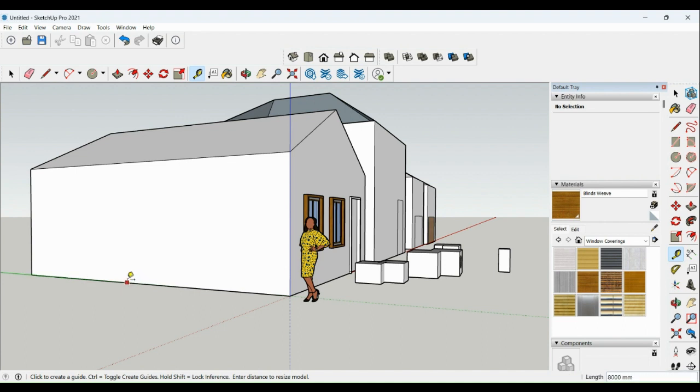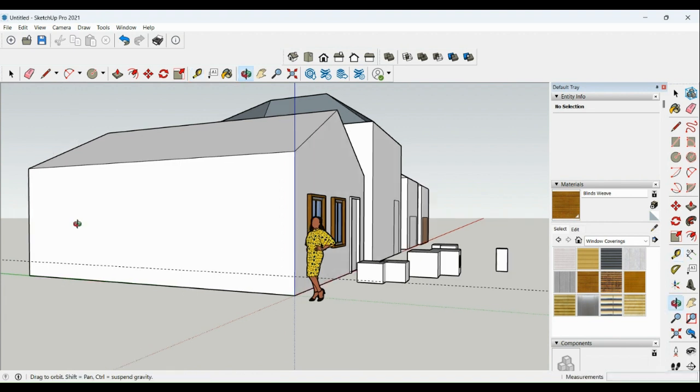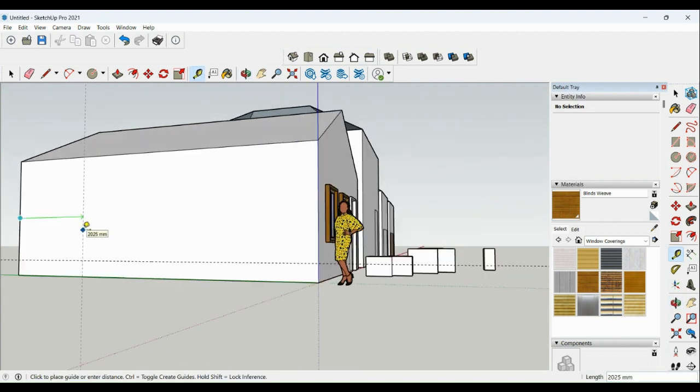Look what's gonna happen. I will click this here in the midpoint and lift it up like that, and you see guidelines coming. So now the bottom of my window, let's say I will make a big window here. It will be like 400 only, so I'll type 400, enter. So I have that guide for the bottom of my window. Again, from this side, I'll take that midpoint and go to the right, and I will make it let's say 2000 from that edge of the wall.